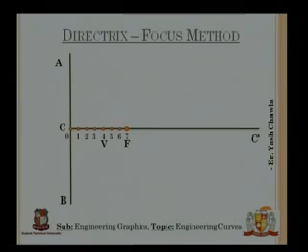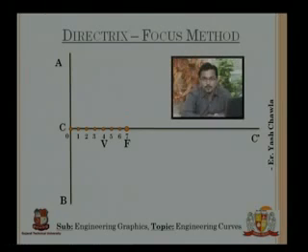My eccentricity ratio is 3 by 4, so the point through which the ellipse will pass on this axis will be 3 points away from F and 4 points away from C. So from C, 4 points away, I have marked this point V. This point V will be one of the end points of the ellipse, one of the points on the extreme left hand side of the ellipse on your screen. I hope you understood why I have marked point V 4 clicks away from C and 3 clicks away from F.